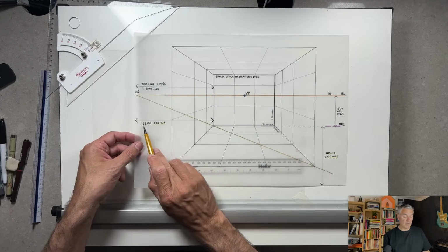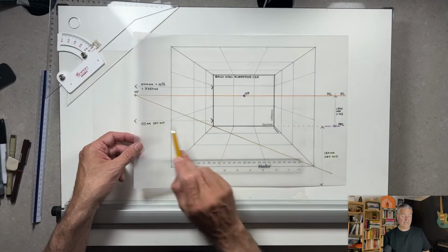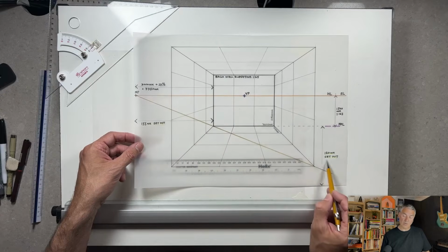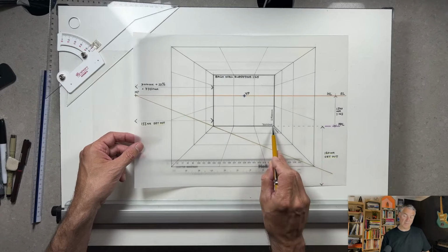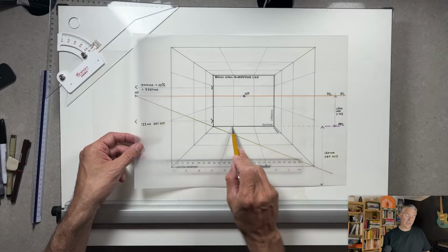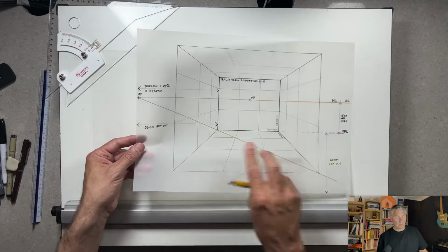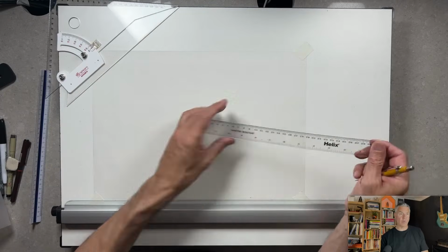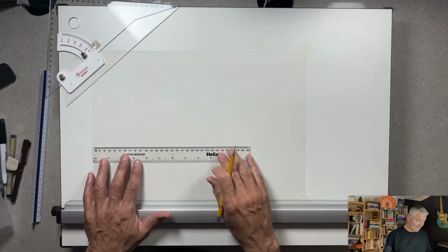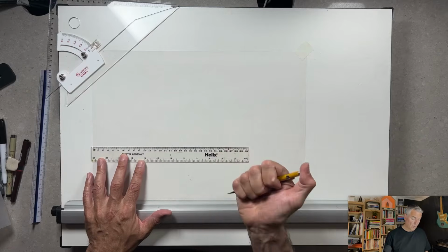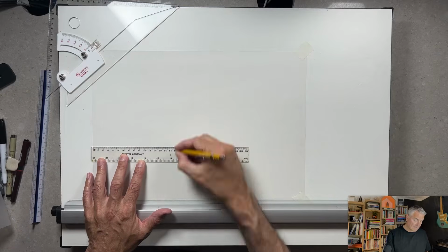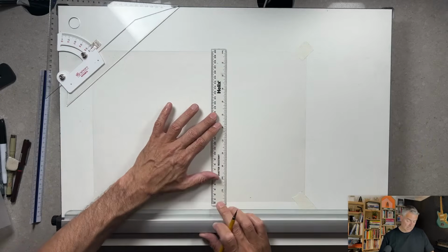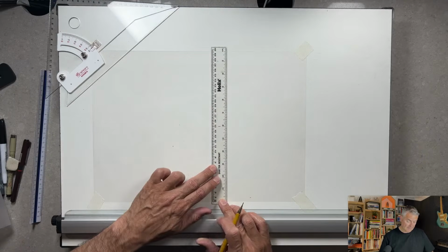So it's 155 millimeters from the edge of the page, and you can draw a vertical line, and it's 120 millimeters from the bottom of the page, and then you can draw a horizontal line here. So that will help us set the drawing out. I'm going to do this on a normal ruler, so we're not using scale yet. 155 millimeters over and 120 millimeters up.